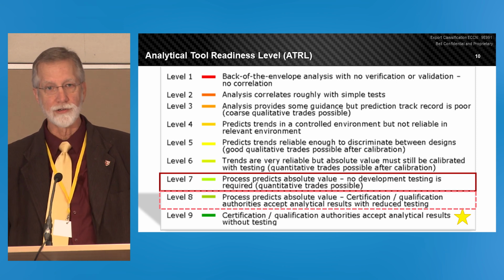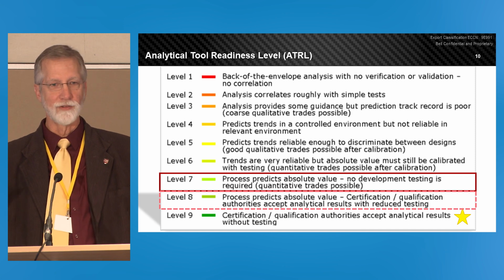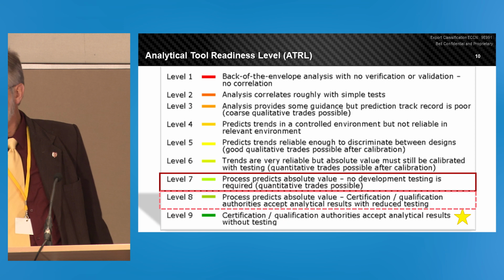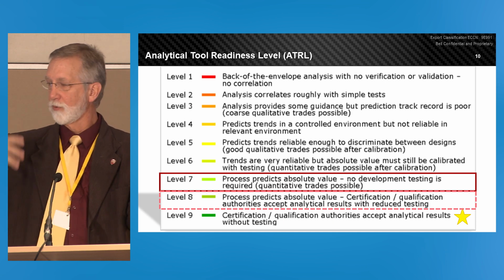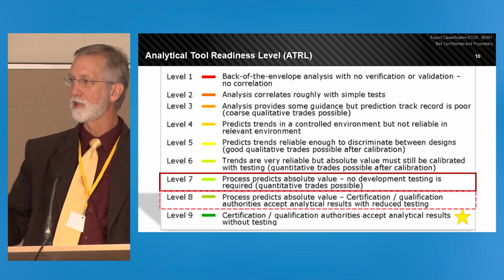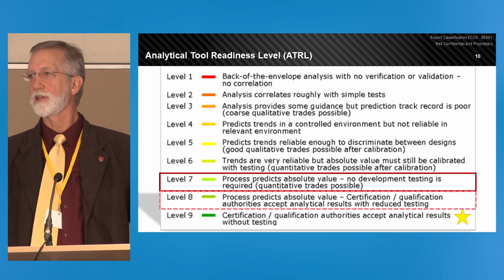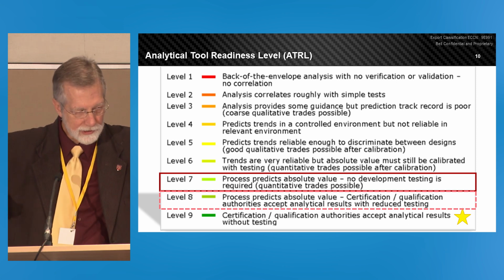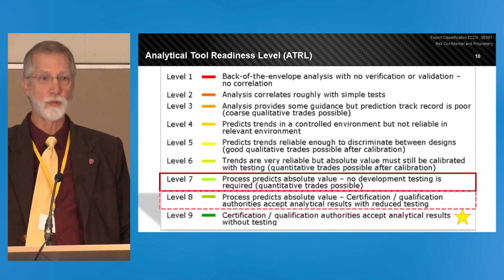There was something wrong with the test, and sure enough, when you go in there and you look, the material properties were wrong. There was resin starvation in there. The composite wasn't per the drawing. I mean, there's a conformity error there. The test article did not match up with the test design part. The design was what we analyzed. It would have passed. So we reanalyzed the system with the reduced material properties. Remember I told you it starts with physics first, get your material properties right, and voila, completely replicated what we saw in the test with the dramatic failure. That to me was one of the strongest cases for the fact that analysis, we nailed it. And you can have high confidence when you're at an ATRL level of 7 or 8 that the analysis is right, and you dig back in and you find out some problem with the test, okay?